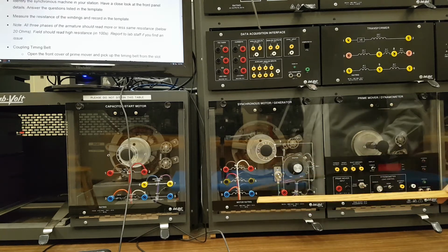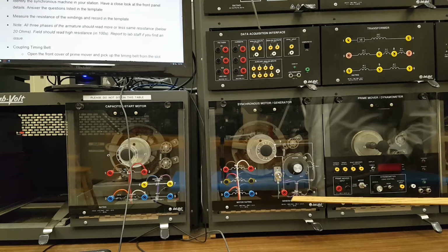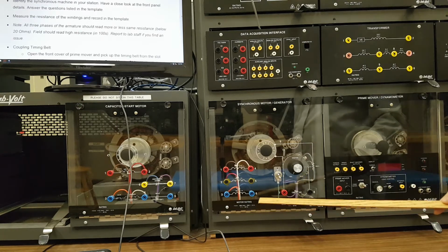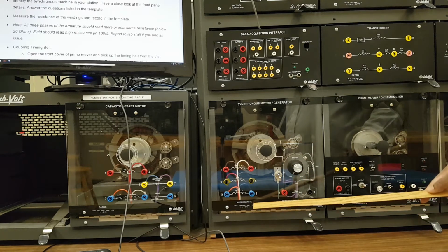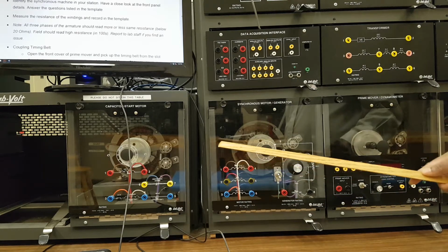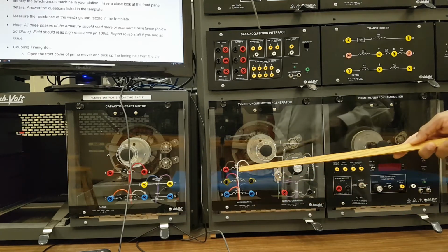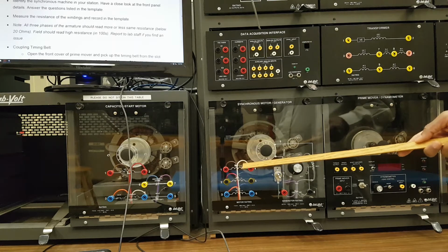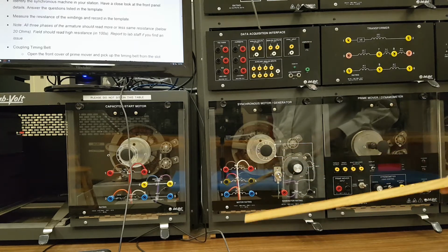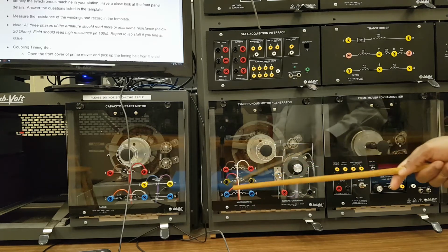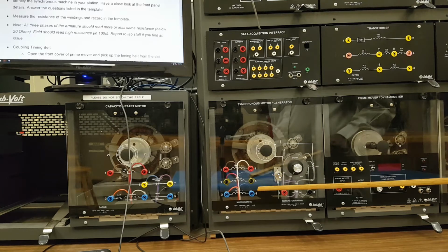So when you have to design, you have to consider the highest current rating, and instead of exactly putting 0.8 amperes as a rating, you would incorporate some safety factor also. So that is the reason this 1 ampere is there. That means it has a safety factor kind of thing. Okay, so that is the idea of this one.